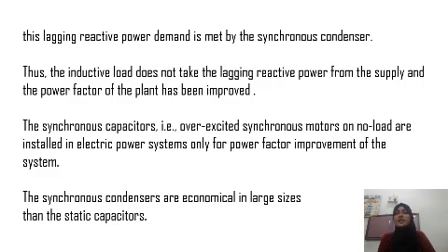Thus, the inductive load does not take the lagging reactive power from the supply, and the power factor of the plant is improved. The synchronous capacitors, that is over-excited synchronous motors on no load, are installed in electrical power systems only for power factor improvement of the system. The synchronous condensers are more economical in large sizes than the static capacitors.